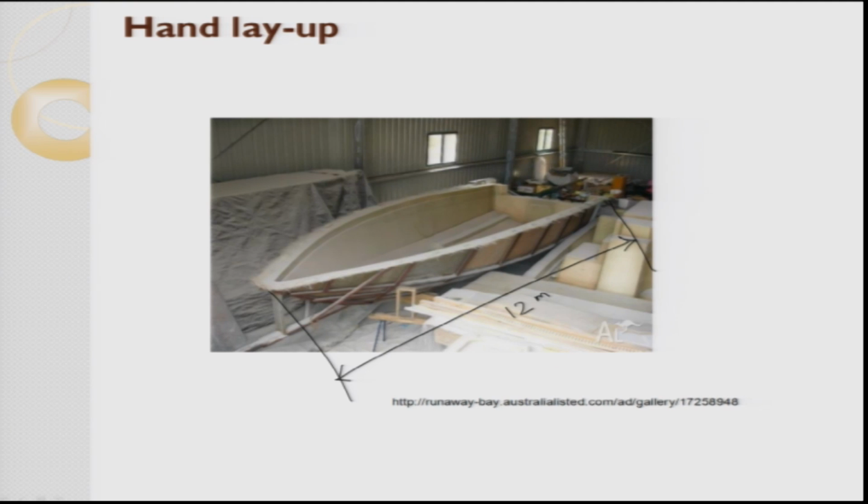Here, if you see, the top surface we are not worried about surface finish. The bottom surface is very smooth, and here is a mold. On this supporting structure, inside you will have a wooden mold or wooden pattern made, and then on top of it you do the layup. These are the projections because of the fiber, so they are all trimmed before giving to the customer.